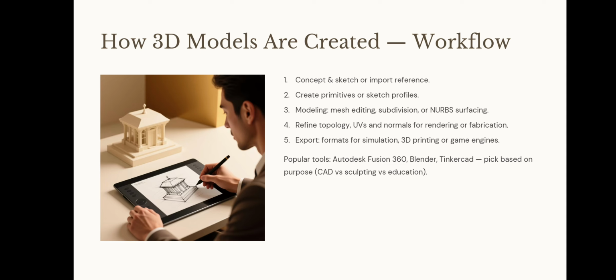How 3D models are created. Workflow. First, concept and sketch, important reference. Second, create primitives or sketch profiles. Third, modeling, mesh editing, subdivision or NURBS surfacing. Fourth, refine topology, UVs, and normals for rendering or fabrication.